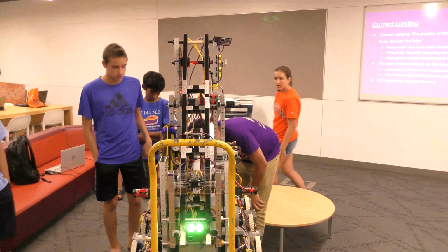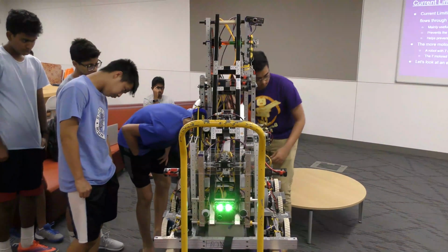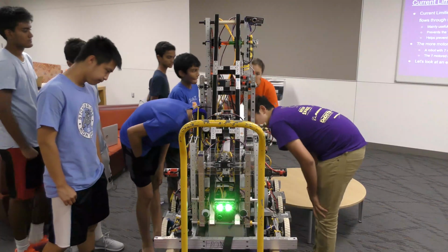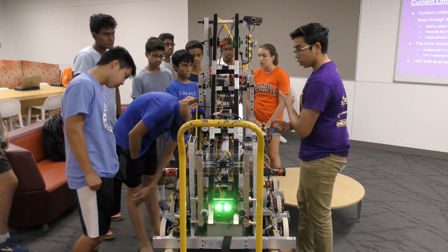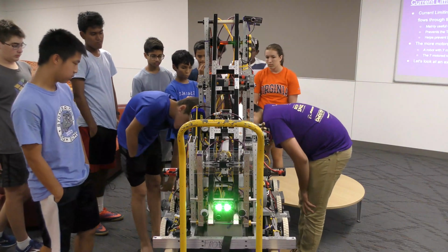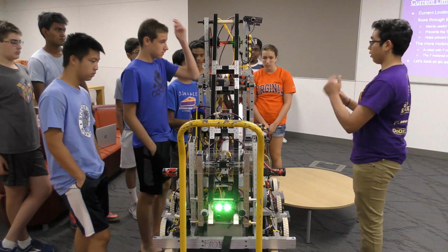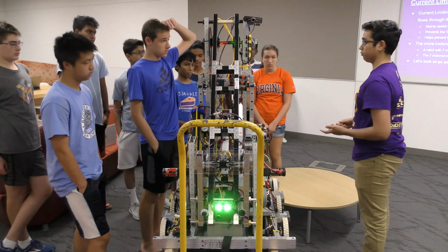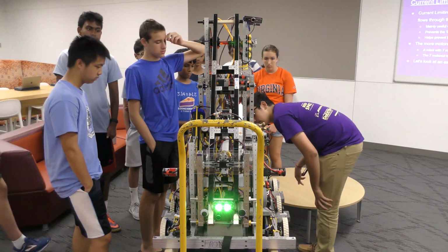So on the PDP, I don't know if you see these little black things over here. Oh, I see them. So those are physical components that help prevent too much current from flowing through the PDP. So if there's too much current flowing through there, the breaker will pop, and that'll just break the connection and prevent more electricity from flowing through. So it's really loud and you can hear pretty well. We had a lot of breakers pop this year.